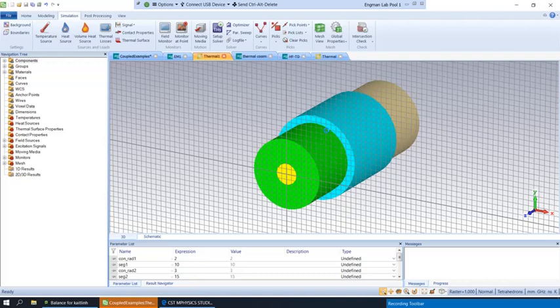However, there is a hang-up, which I alluded to in my previous video, and that is that they have failed to provide us with any information about the density or the specific heat. And so I argued that that would limit the solvers that we would be able to use, and in fact it might make it so the simulation doesn't work at all.